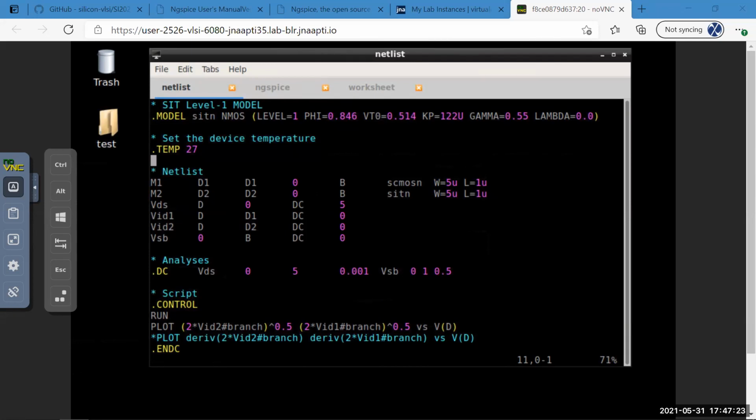Yes, sir. So that's my guess, that you guys are making a mistake in your netlist and you're running out of RAM. Basically all your machines have only 500 MB RAM. Just remember that. These are tiny instances running in the cloud.